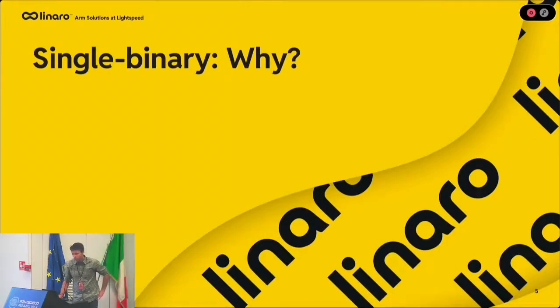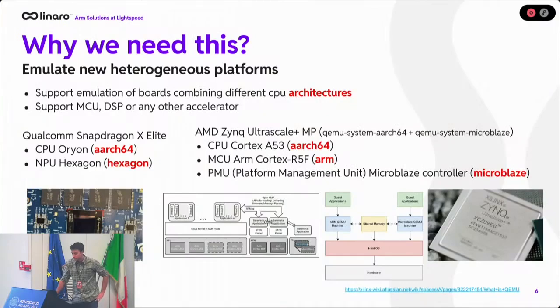So why do we need that? As I said, our goal is to be able to emulate platforms that are mixing several architectures. This is what we call heterogeneous platform and heterogeneous emulation. The use case is mostly to model some boards that have a main processor, microcontrollers, DSP, or any other kind of accelerator, and be able to emulate all that in a single QEMU process.